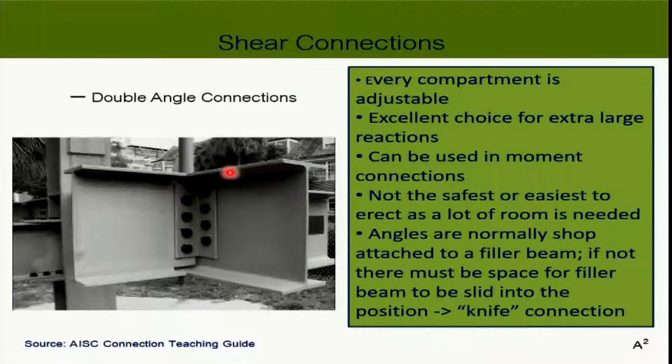And not the safest one or the most economical one because it is big. And sometimes, if you can, we attach the angle to the beam and then bring it to the side and then connect the beam and the angles to the support. Okay, all right. We have 3 combinations for this. I don't know why I began with this, but can we just skip this too?